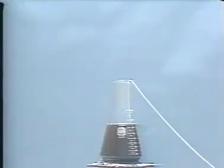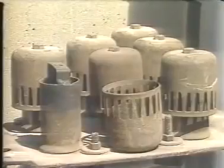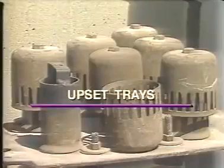When trapped water vaporizes to steam, it can pose a grave safety hazard because it expands 1,600 times in volume. Sudden vaporization of water causes pressure surges that can damage internal tower hardware and, in extreme cases, can even rupture a tower. Another condition that can interfere with normal operations is upset or damaged trays.